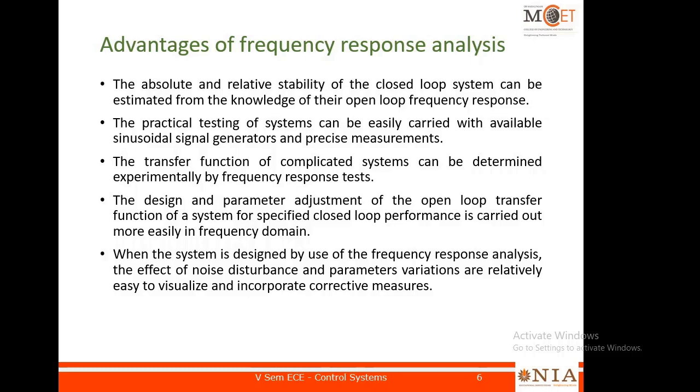There are certainly many advantages in doing frequency response analysis. One main advantage is, for an open loop transfer function, if you draw the frequency response, then you can estimate the relative stability of the closed loop system. So there is a connection between open loop transfer functions, frequency response, and relative stability of the closed loop system.